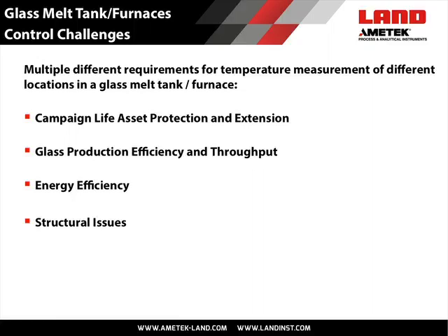In glass production efficiency, the blanket, melt line, and batch transit time can be visualized, recorded, and compared. For energy efficiency, burners can be optimized from viewing their propagation and burn efficiency and their impingement onto various areas. Structural issues can also be determined. Early temperature visualization of cold spots in the refractory walls, possibly indicating air leaks caused by structural issues, can be detected.